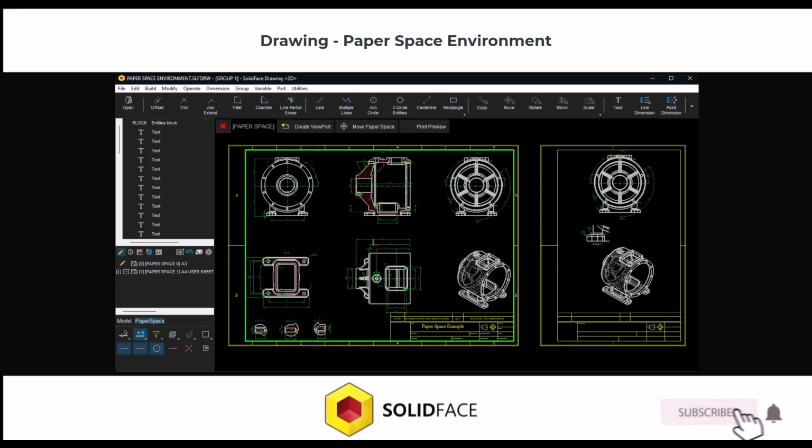Explains how to insert sheets into a drawing using two methods: insert sheet as paper space and insert sheet as drawing. It details the process of creating a paper space environment with viewports and the insertion of sheet templates. Additionally, describes creating multiple paper spaces, inserting geometries and texts, and tips for efficient visualization in complex drawings. Finally, it emphasizes the importance of correct sequencing when defining geometries, texts, or blank viewports to avoid the need for frequent edits.